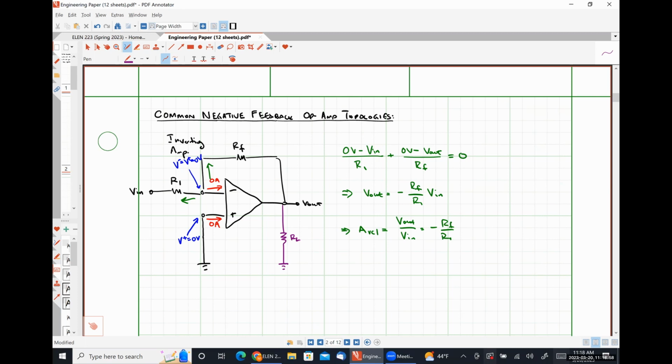No, not even a little bit, right? So the presence of a load resistor here does nothing with respect to our output voltage. It is going to have some effect on whatever current is flowing out of the output terminal because there's another conduction path, but largely we don't worry about that a whole heck of a lot. Although I definitely ask you questions about it in your homeworks.